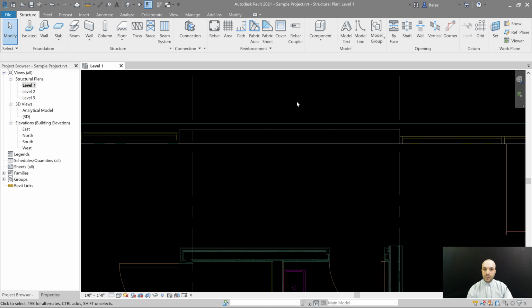And now you can see that Revit gives me a hidden line because it's communicating back with me. I had selected on the options bar that I needed the location line to be finished face exterior. So now Revit is asking me, you're using the pick lines tool, is this where you want the wall to go? And I say yes by clicking. And there you go.